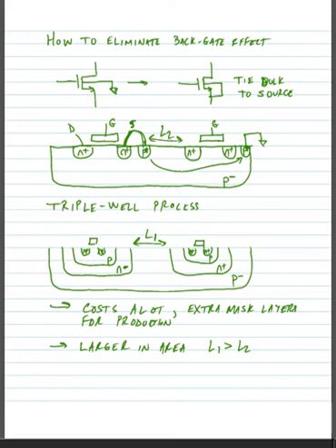So the modification that we're going to make to our small signal model is that, for instance, in our common source amplifier, Vo over Vg, our gain, is equal to Gm times RT still, but in this case we're going to say that Gm is equal to little gm divided by 1 plus (gm plus gmb) times Rs.